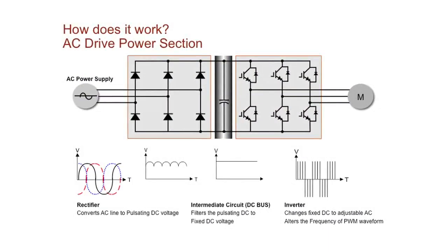A few basics about how an AC drive works. In an AC drive, we take the AC line, we send it through what we call a DC bridge, and we create a DC bus. And that bus then, the bus voltage level is kind of governed by the level you put in over here. So if you put 460 volts in on the AC side, you're going to get a DC bus in the 650, 700 volt range. Here's the input 3-phase AC signal.